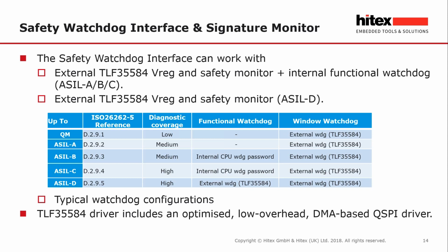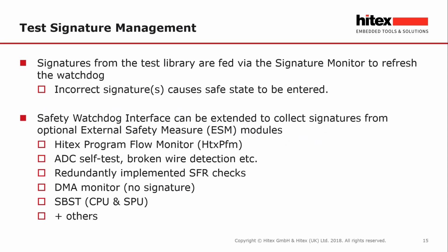The lowest level driver to the TLF 35584 is a specially written high-speed optimized DMA-based QSPI driver. So we're not relying on a QSPI driver from another source. This is one specifically written for the job.